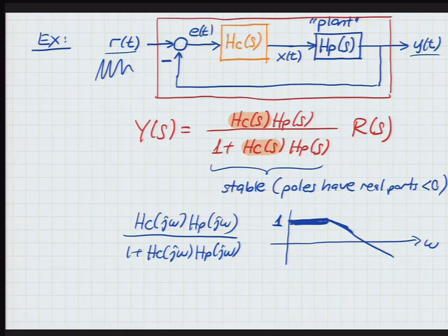When you look at things in the frequency response, there are actually very interesting and very powerful design tools that people in industry use. They sometimes call it loop shaping, because one interpretation of what you're doing with feedback is really shaping this loop. There are usually conflicting criteria. You would like this to be 1 for as long as possible, but keeping that to be 1 also makes you vulnerable to noise in your measurements and disturbances that are acting on the system.